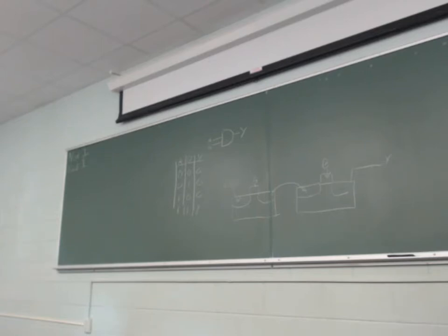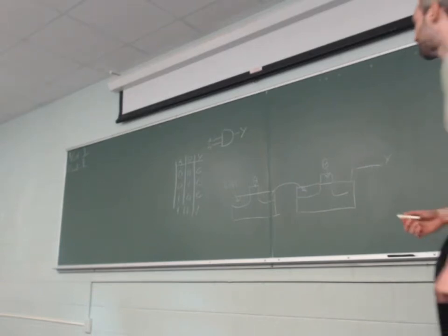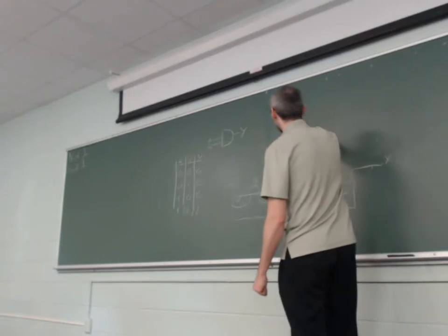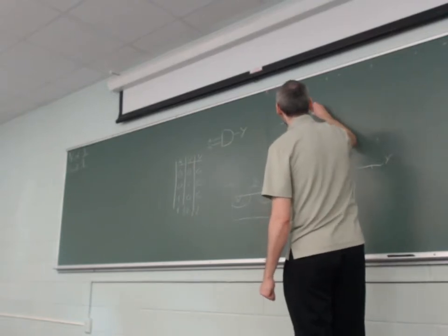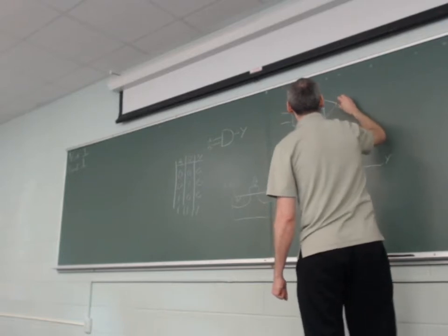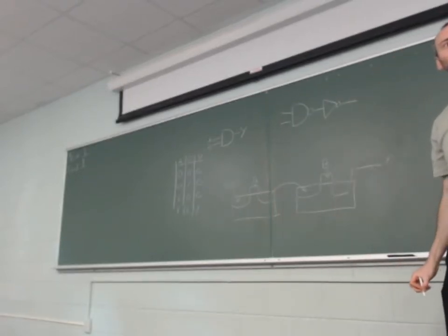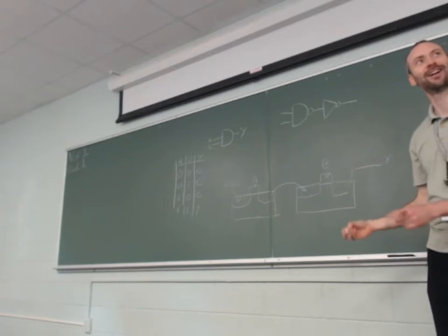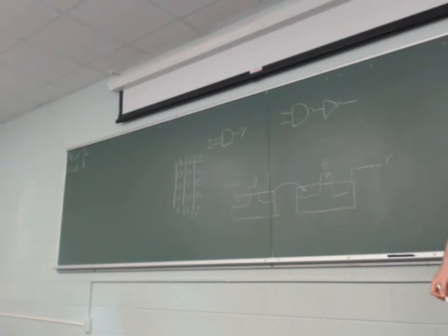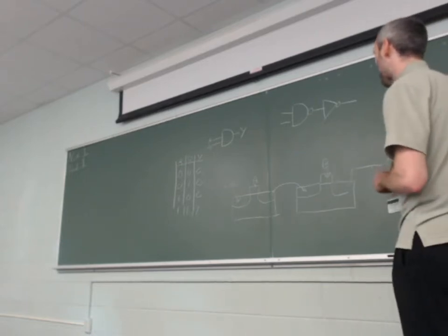Well, there's different ways to go about it. Let's do the easy way first. We already have a NAND, and we already have a NOT. So we just add the NOT to the NAND. Right, so we could do this. Because you NOT the NAND, you NOT the NOT of the AND, you get back the AND. So luckily in circuit diagrams, NOT NOT A equals A. So that would work.